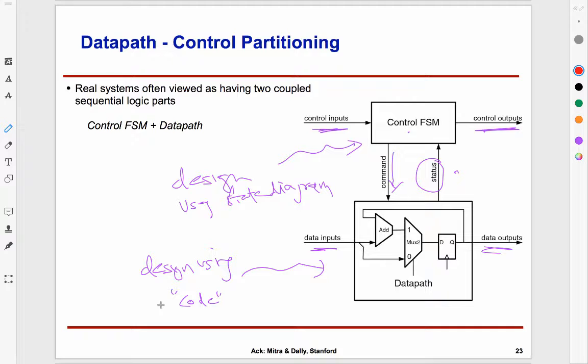Controller is one which we implement using the techniques we did first, namely a state diagram and things like that. It will usually have a small number of states, which basically means it will not be dealing with n-bit chunks. It will be dealing with signals which are single-bit signals or maybe a couple of bits, 3 bits, something like that, not n-bit stuff. Okay, and then I'll have the data part, which is referred to as data path, and that is where we are going to be primarily manipulating n-bit entities, but under the control of signals which are 1-bit signals.